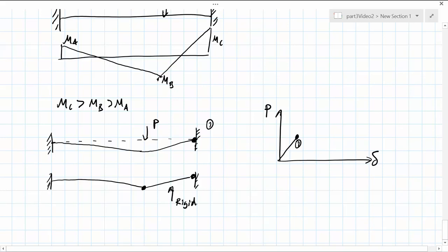It loses its elastic deformations, whereas this section still remains elastic. The next hinge to form then adds to the load deflection curve, and it's showing a gradual change in gradient indicating yielding.